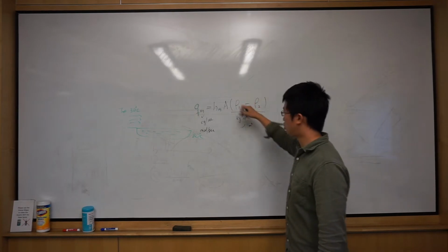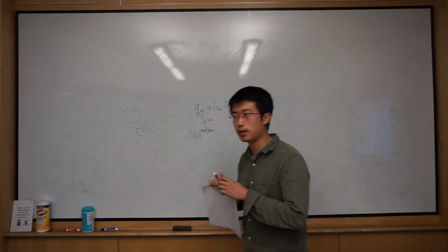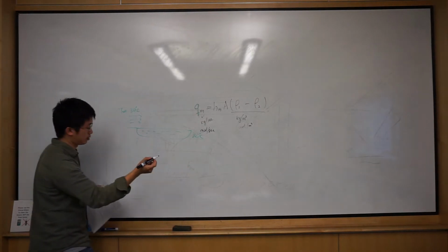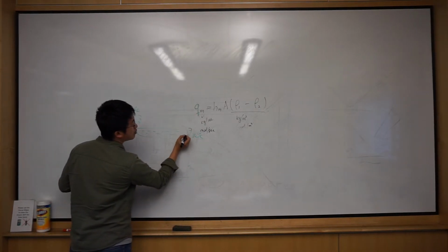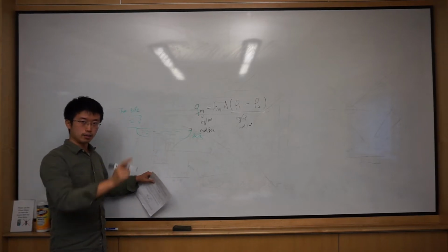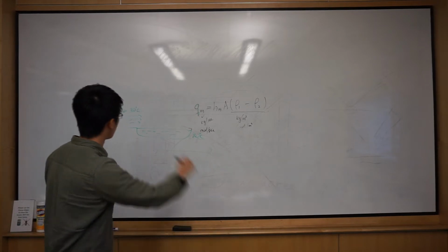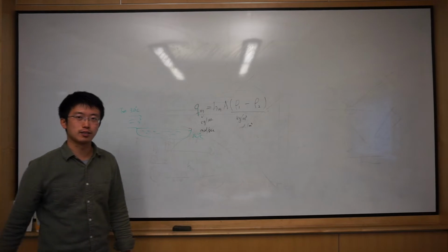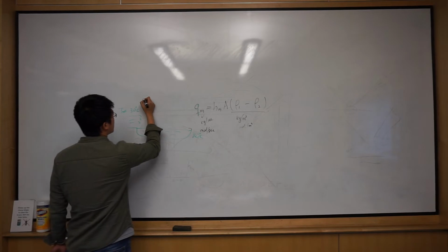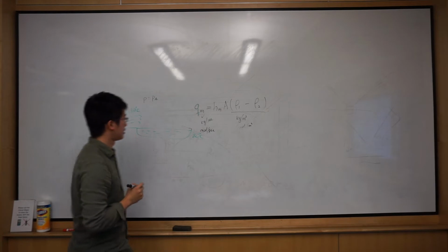Then how to evaluate these two cases? Then we're using some knowledge from Thermal 1, ME200. So for the first one, it's an assumption. So basically at a very close neighborhood of the water surface, we assume there's a phase equilibrium. Oh, by the way, there's one hidden condition we didn't give you, but you should definitely know: the pressure is at atmospheric pressure, right?